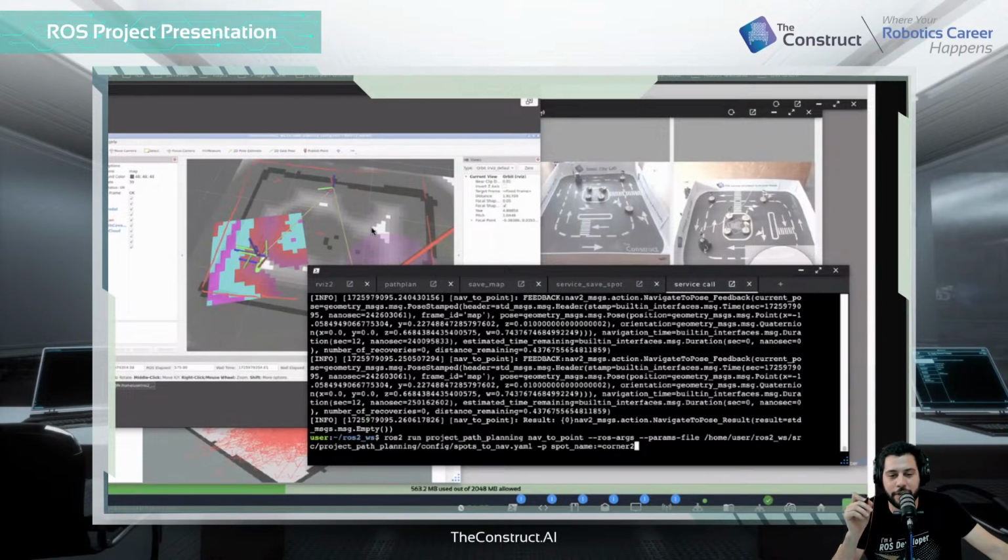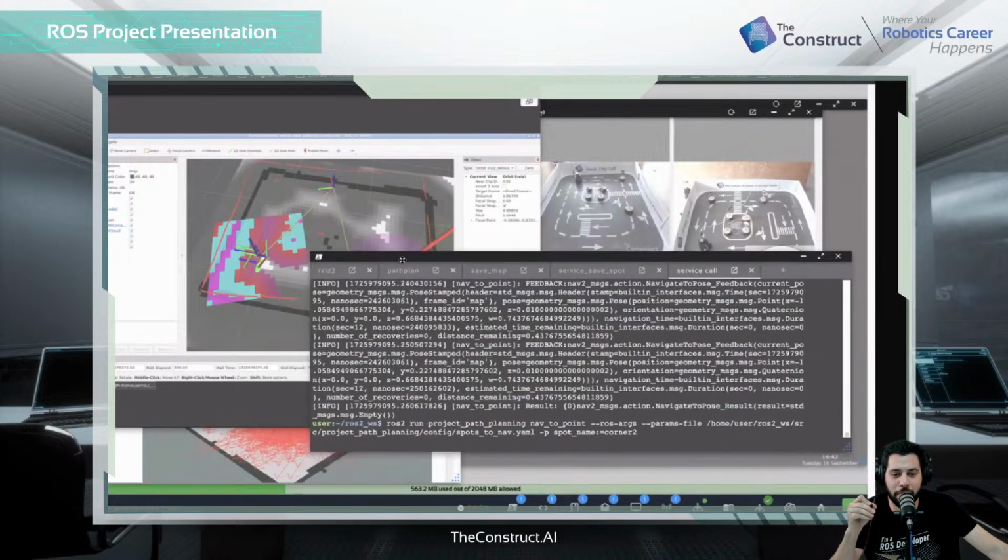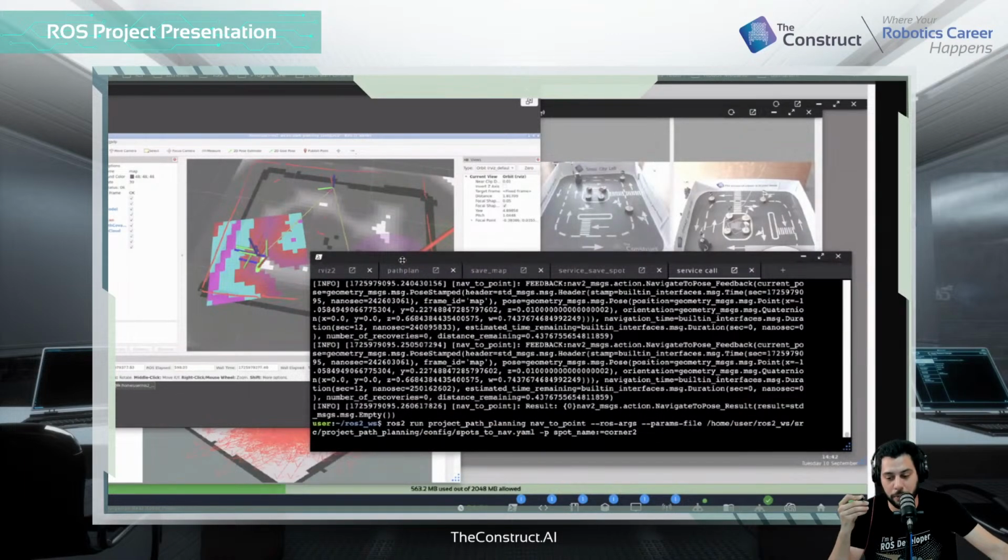So the main point here is that if you are not seeing the cost maps, I think the issue is setting the QoS topics so that they must match. And then there's a weird thing in the parameter files for your navigation setup, in the local cost map and global cost map. You must set all the booleans, so true and false, to start with a capital letter instead of a small one.